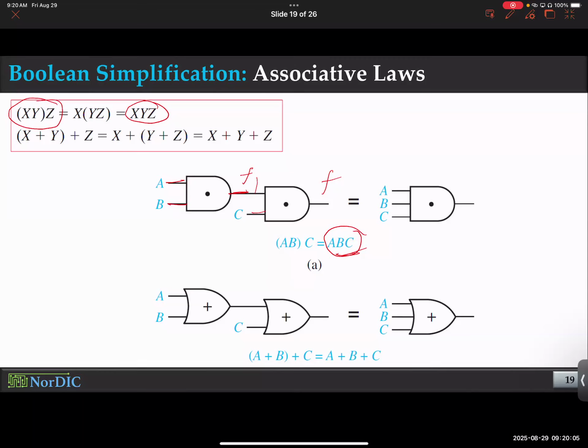And we explained that in 433. Literally, we compare between, so if you see a diagram, a plot, this is propagation delay for high to low switching. Literally it goes up like this with n being the number of inputs. So the more inputs you handle simultaneously, the slower the circuit becomes because the delay goes up. Okay, there are reasons, we discussed this, but for now we're just going to ignore it. But know that yes, this thing is a design decision.